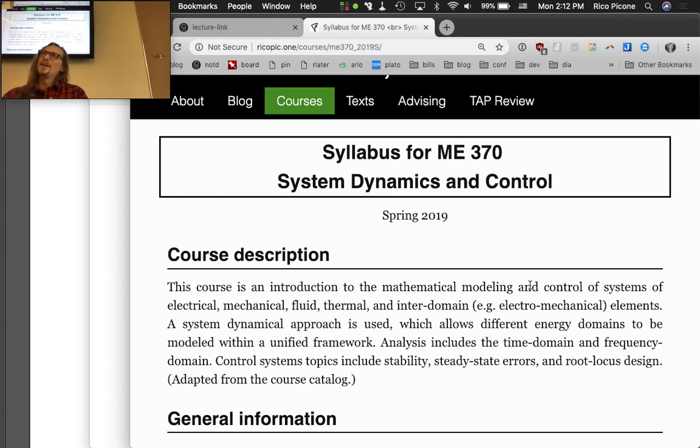I think I'll give you guys one heat transfer problem though that does that, and it shows you how you can use this, extend this stuff to finite element approaches. So we're doing this sort of system dynamics approach, lumped parameter modeling. The mathematical models that we'll get will be ordinary differential equations, because they're not distributed through space, just time. So we have ODEs to solve to find out what the system will do in response to some input, right?